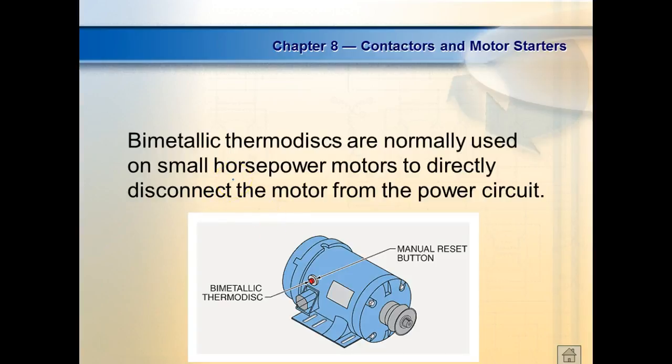Well, there's 2 ways you can reverse a DC motor. You can change the connection on the field, or you can change the connection on the armature. The industry standard is to change the armature because of all kinds of reasons. We'll look at that later. But they kept saying you can change the field. Yeah, you can change the field, but that's not the way you do it in the industry, because it can cost. And they had a question on the test like that in Georgia.